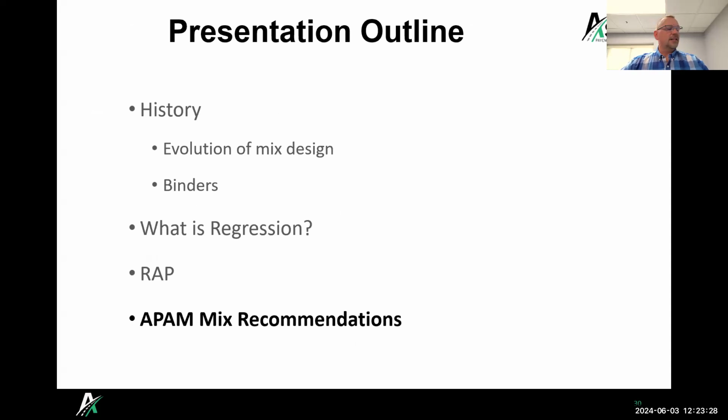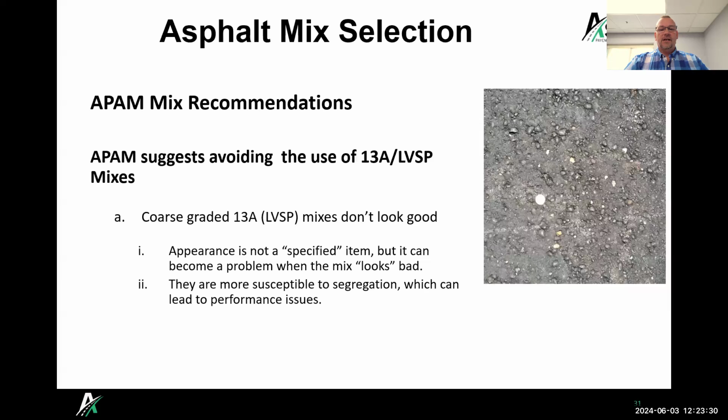So just quickly, I want to talk a little bit about mix recommendations. And really, APAM suggests avoiding the use of 13A or LVSP mixes as top courses. Really, appearance isn't a specified item, but it can become a problem when the mix looks bad. And the problem with 13A and LVSP mixes is the gradation band is very wide on them. They can be coarse graded at times, and they're not a pretty looking mix.